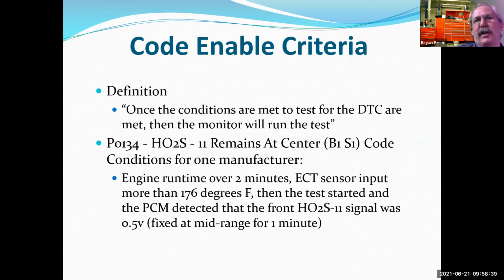I mean, why test everything if, hey, 800 people say this part fixes it. Okay, let me go test that part, since that seems to be the one that's going bad and the dealer has 10 on the shelf. I'm thinking that there's a high likelihood here. So we use it for setting priority of diagnostic testing, also helping us with diagnostic testing. So this is a huge thing. And unfortunately, this is a step that many technicians skip. I don't want to take the time to go look up that stuff. It takes too much time. Well, how much time are you going to waste fumbling around in the dark?